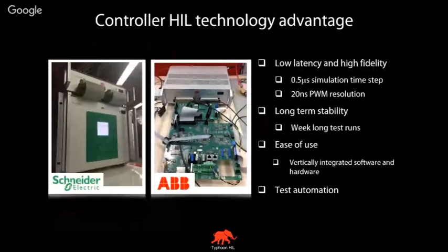Now, this is of course only on the converter level. This is how the technology started, because if we compare power system dynamics to converter level dynamics, we know that converters are switching at very high frequencies, which demand very small simulation time steps on which these computers have to perform. So the biggest demand was exactly on the converter level.